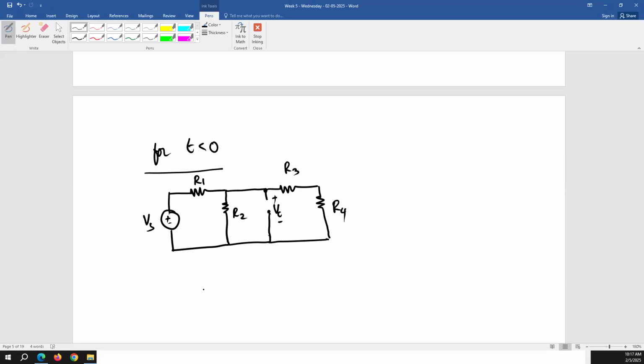Once you have two resistors connected, R1 and R equivalent, then you are trying to figure out the voltage across what? R equivalent. And you can apply voltage division easily. You don't have to go all the way and calculate current, though you can do that. There's no problem with that.